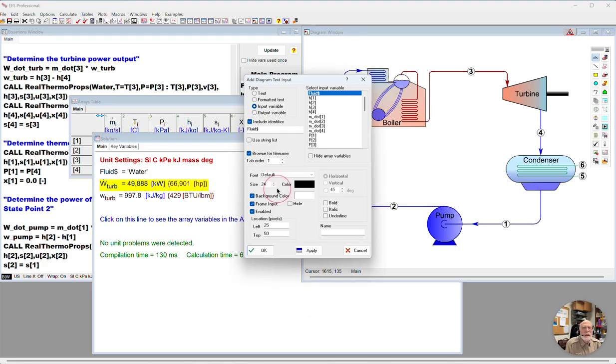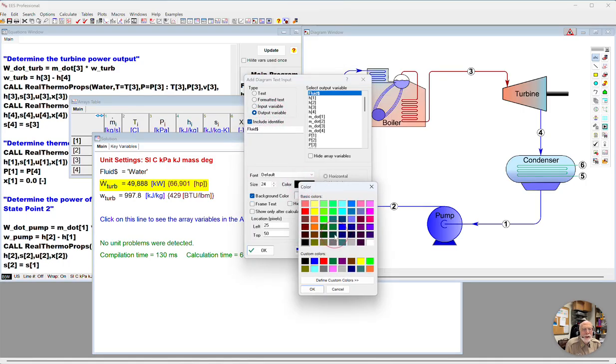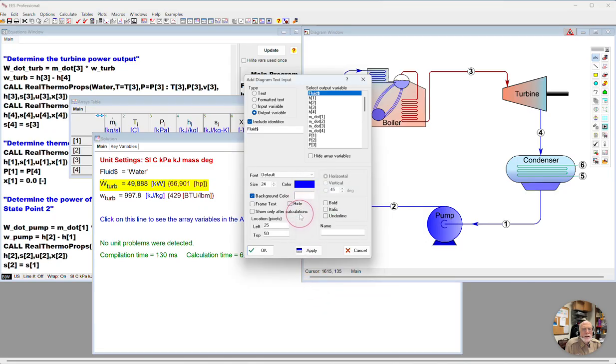The input variable is if we want to use this as a graphical user interface, in essence, a GUI. So we might do that at the end of this lecture. The first thing we're going to do, though, is put output variables in. I will generally make my output variables in a dark blue, and my input variables I typically make a dark red. So we'll get to that when we get to that. In the meantime, you must click OK here for it to register.